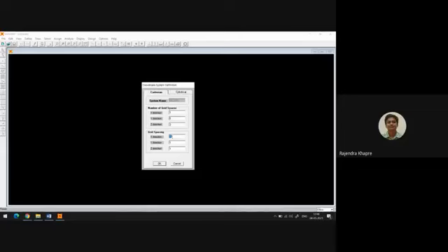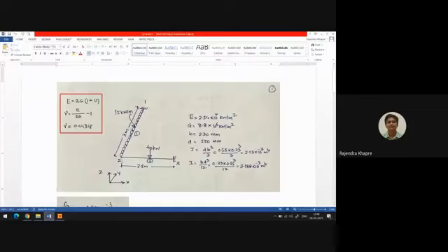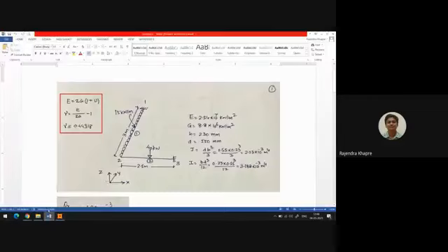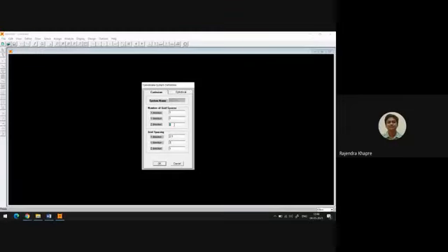Along the Y axis, only one grid space is required, at a distance of 3 meters. If you refer to the Z axis, which is the vertical axis, I don't want any grid in the Z axis, so I'm keeping this as 0. There is no point in giving spacing because there is no grid in the Z axis.